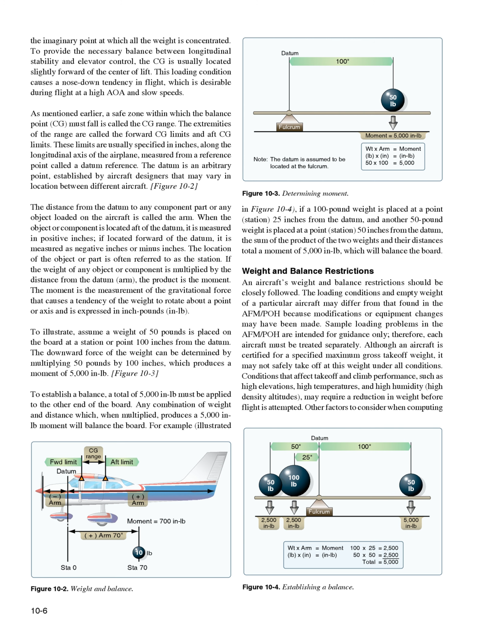Weight and balance restrictions. An aircraft's weight and balance restrictions should be closely followed. The loading conditions and empty weight of a particular aircraft may differ from that found in the AFM/POH because modifications or equipment changes may have been made. Sample loading problems in the AFM/POH are intended for guidance only, therefore, each aircraft must be treated separately.